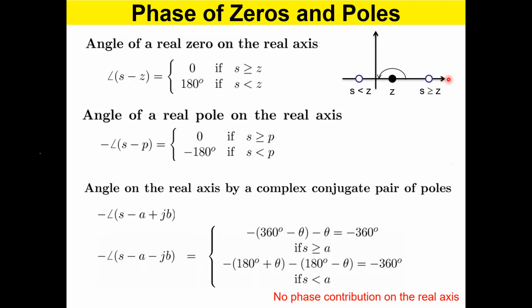And also I want to tell you one thing: the root locus is symmetric around the real axis. So if you have something above the real axis, you have the same thing below the real axis. Okay. Now let us take a pair of complex conjugate poles, because this is again very common. Just a while ago, you dealt with a pair of complex conjugate poles. Remember, the two poles move head on and meet up at a point, the critically damped condition. After that, one goes north, the other goes south, right?